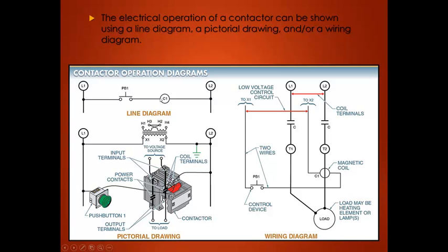When this is energized, the contactor pulls in, we say. It closes its contacts. So C1 closes these contacts, which then turn our larger power source on, or connects it to our load.